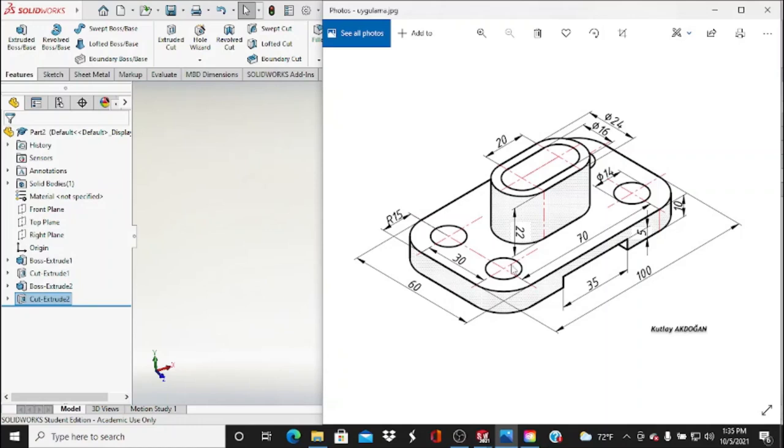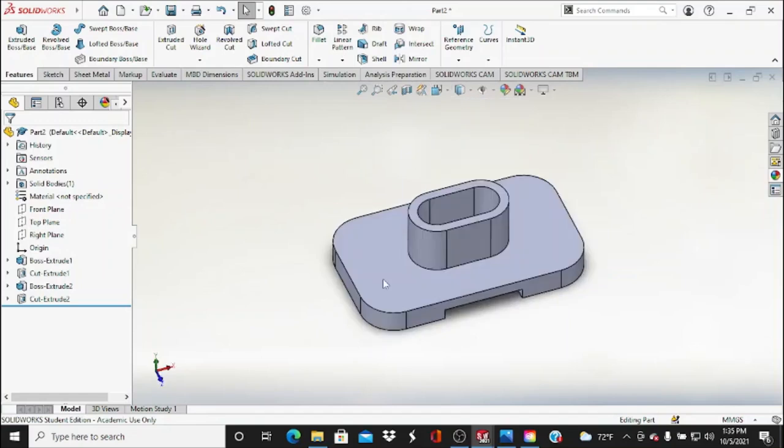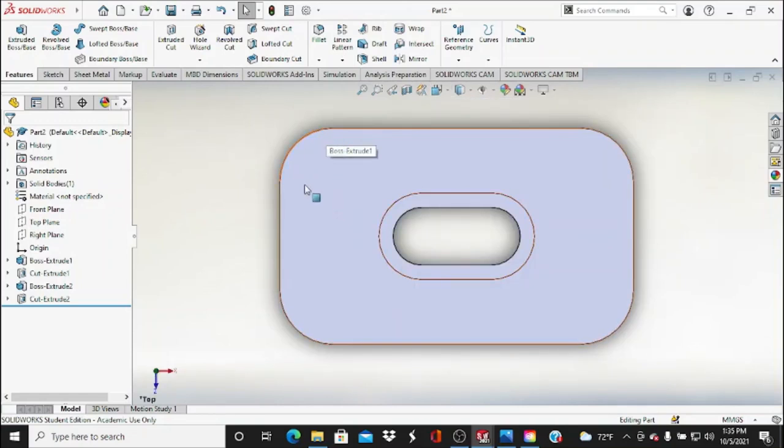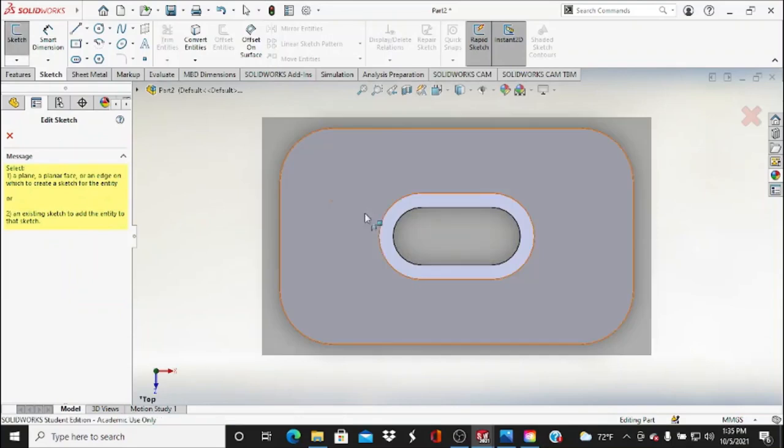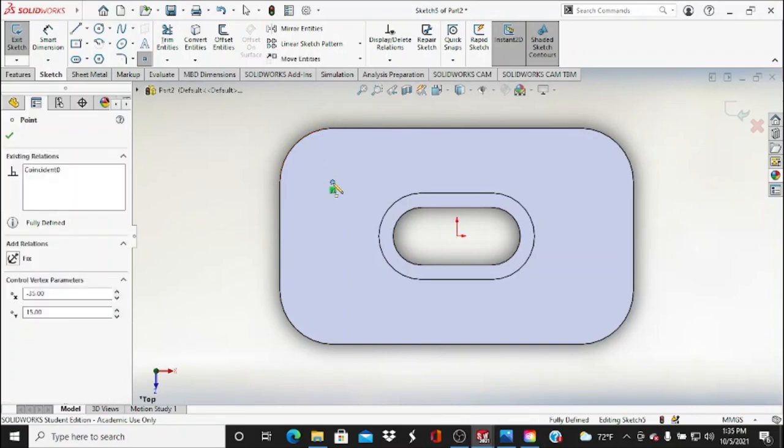So how do we get from the outside from these two? Simple, it's got to be center to the outside, or let's see, I'm trying to look for the offset of it, but I think this right here is going to be about 15 from here to here, and it's going to be on the center of this guy right here, and this one too as well. So our center is going to be at this corner right here, so it's going to be about this tangent right around this area. So I'm going to go to sketch, sketch it out, and we're just going to use the point, that's it. Click it from there, and then we click it to that center right here.